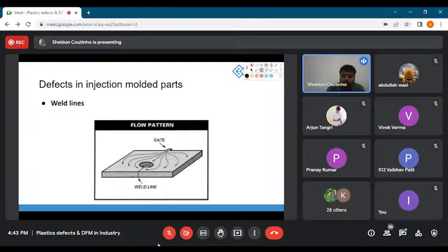a much higher rate. So when you inject your material from here, you will have really warm material to go around and yet have the temperature so that at this point it does not form two different surfaces. It will not have two different surfaces and it will be properly molten.